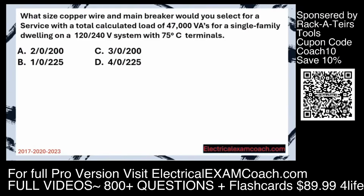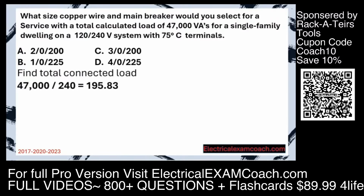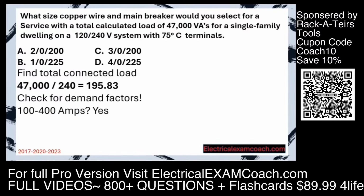What size copper wire and main breaker would you select for a service with a total calculated load of 47,000 VAs for a single family dwelling on a 120/240 volt system with 75 degree C terminals? Step 1, we're going to find our total connected load. In this case, they've given it to us, but we have to divide to get our amperage. When we do, now we can check for demand factors. And in this case, we do have a demand factor. Is this in between 1 and 400 amps? Yes. Is this on a single family dwelling? Yes. So the 83% rule does apply.